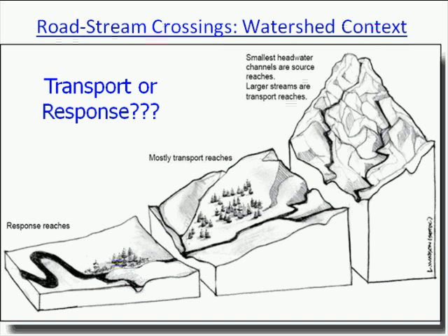We know that watersheds can be segregated into 3 component parts: headwaters, transfer, and depositional. Knowing where a given road stream crossing fits within this continuum will lend insight into a whole bunch of things, like average substrate size, channel gradient and plan form, the relative influence of vegetation on channel stability, and important species and habitats.